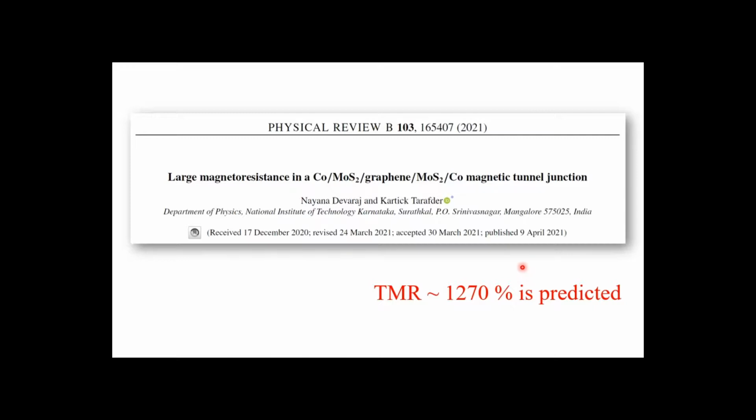So actually, numerous experimental and theoretical studies have been conducted considering different materials as tunnel barriers, but a relatively high TMR was found in Al2O3 and MgO. Even though they were able to produce high TMR values, non-uniform thickness in the device, pinholes, defects, and trapped charges affect the performance of the devices. So by using thin and uniform 2D materials as the tunnel barrier, better control over the morphology of the barrier is possible.